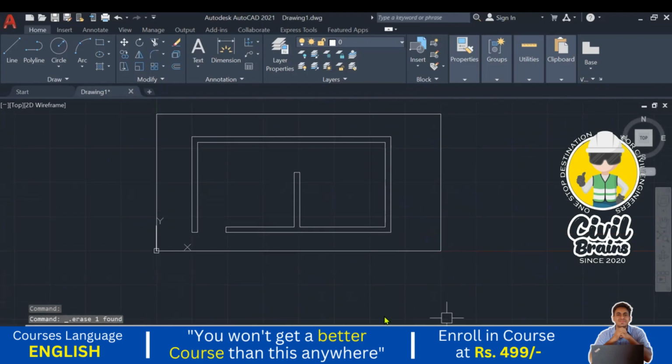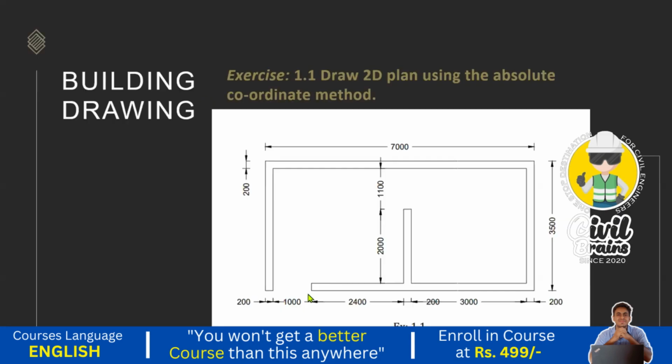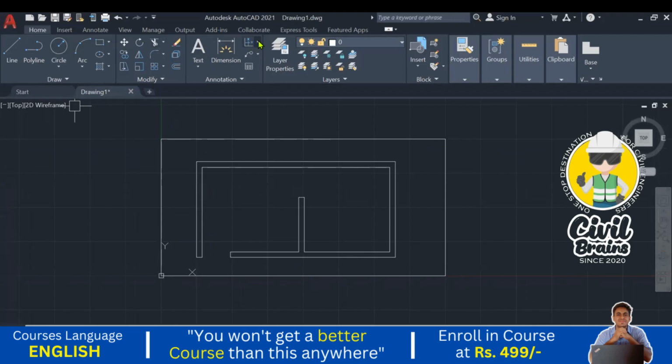So I just open this one. What is the next step? We have provided the openings here, and we also provided the walls. The next step is we need to provide the dimensions. All the dimensions we need to provide. Then the first exercise is over. I just go to the dimensions command. I take the linear. I go here.